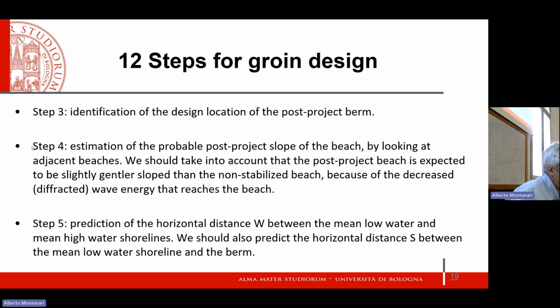Now, step 4, this is interesting. You should try to get a guess of the post-project slope of the beach. Keep in mind that when you stimulate accretion, you get a milder slope of the resulting beach with respect to the situation with prevailing erosion. And this is quite obvious to understand. If you think of a calmer situation, you locate groins, you locate breakwaters, it's a calmer situation in terms of storm regime, of wave regime.